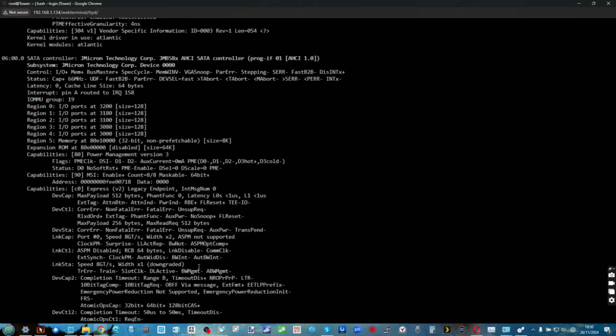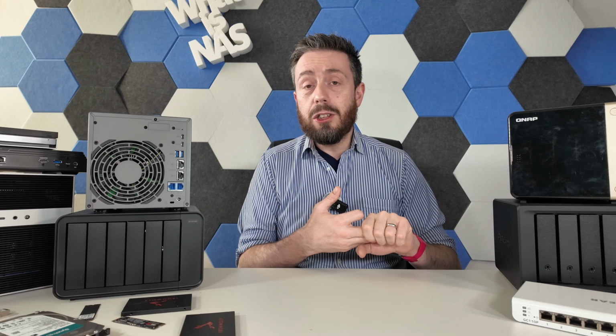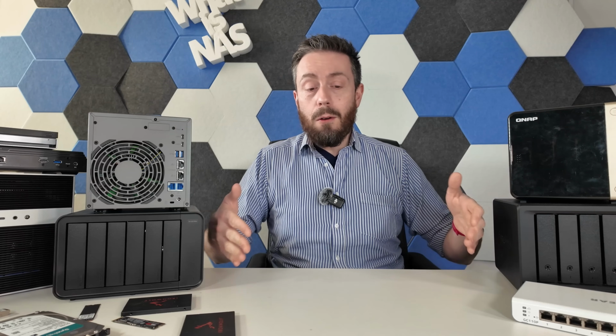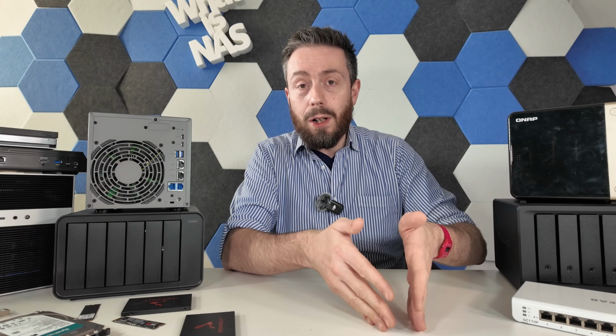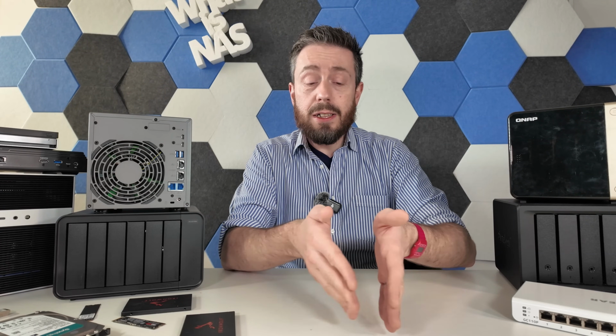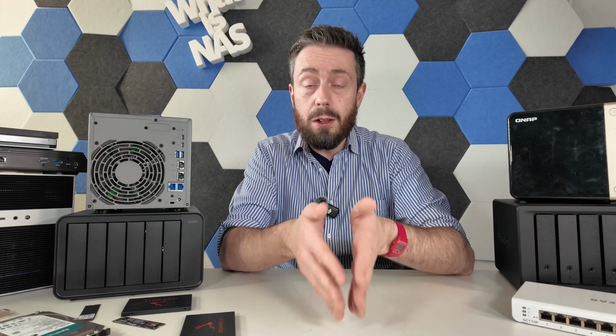Certain controllers inside, ASMedia and Marvell have produced some of them as well that are a bit ropey, but particularly some of the JMicron ones, these are SATA controllers where they feed in and they've been placed on a single 5 gigatransfers ×1 lane. Sometimes this can give you between 2.5 gig and 5 gigabit internal connectivity.